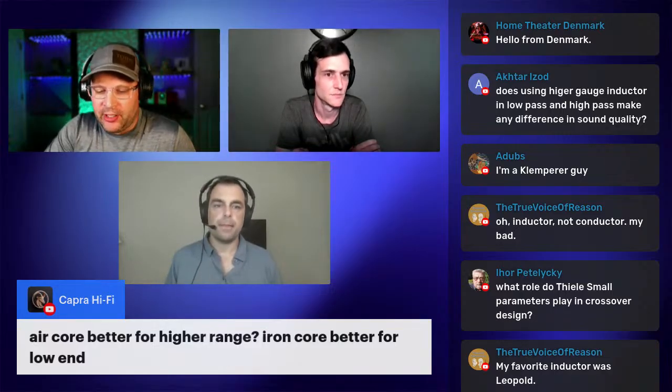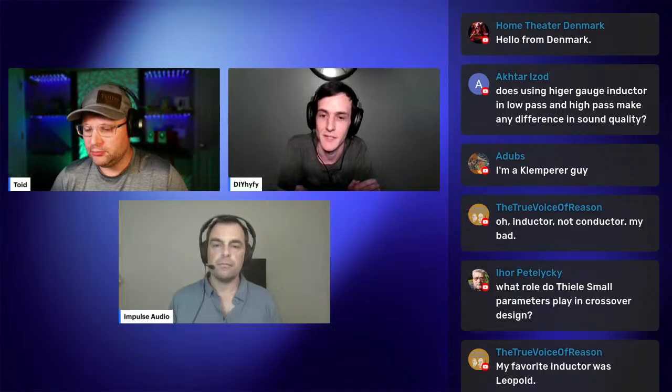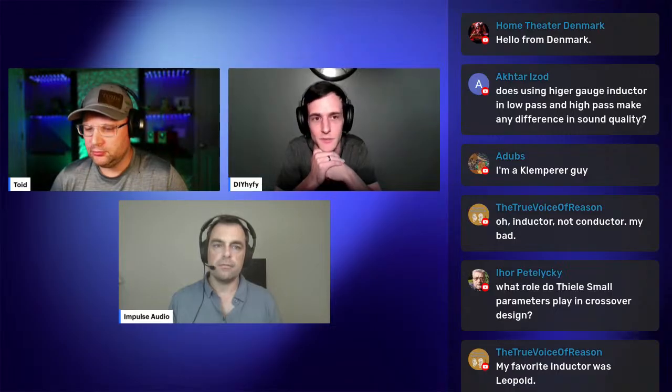And you're absolutely right. That's exactly what I was going to talk about too. Typically, iron cores are usually used in the woofer, and it's mainly cost savings, because when you're buying, say, a 4 millihenry inductor, iron core versus an air core, that's a huge difference in price. When you get into the bigger values, the price difference and size difference can become significant. These steel laminate cores can remain relatively small compared to what you might need on a big air core.